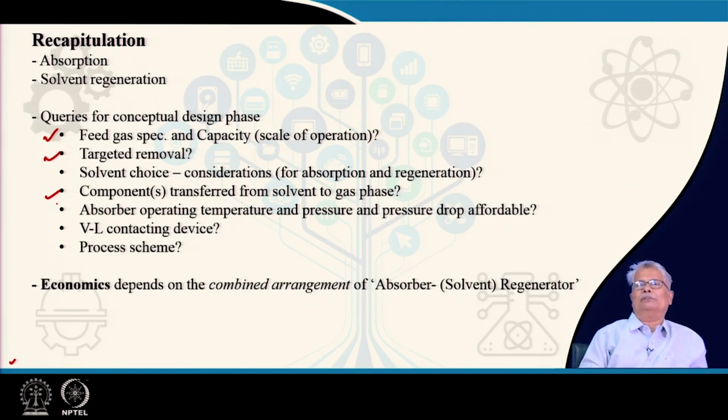So, quite often you will find the solvent before entering the absorber is from a cooler. The pressure plays a key role in the solubility of the gas in a liquid. So, quite naturally, the higher the pressure, the more will be the carrying capacity of the solvent with respect to the solute.